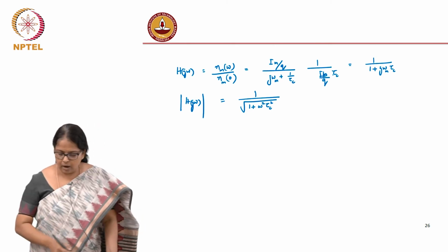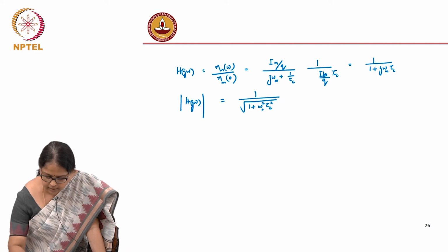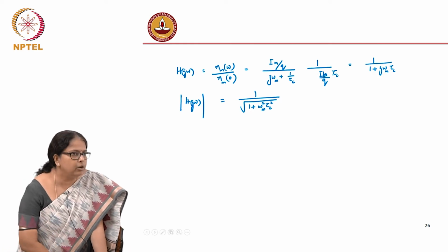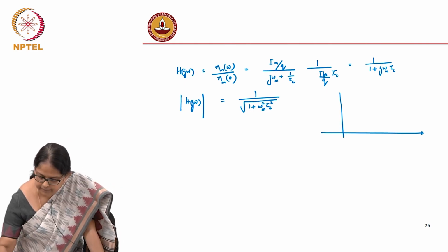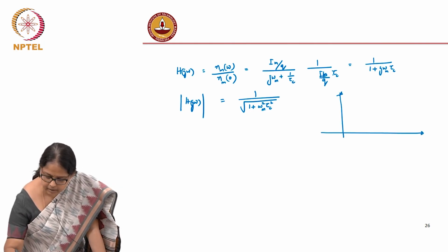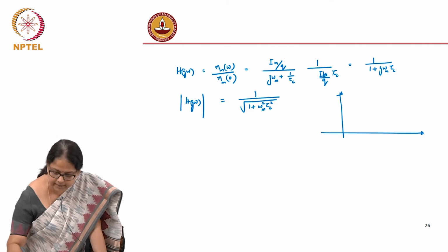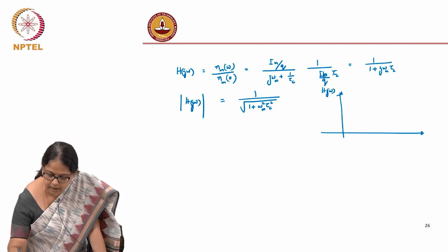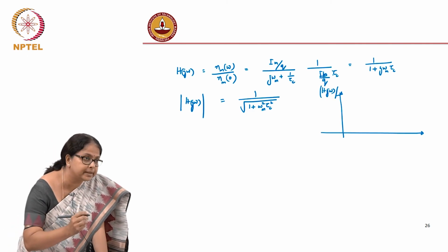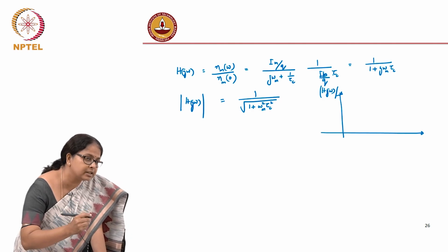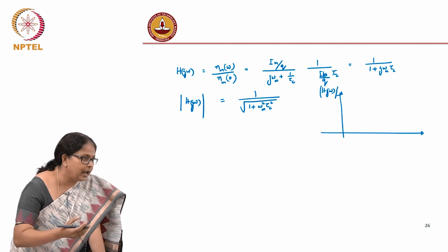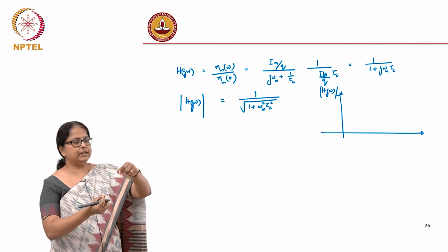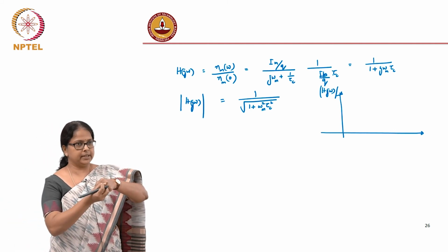Okay. So, this is omega m, how do I now try to plot this? As I increase my, now what should be my y axis? Y axis is of course h of j omega, but what does this h of j omega actually represent? It represents the response of your carrier density, and we assume that electron hole recombination is an instantaneous process.